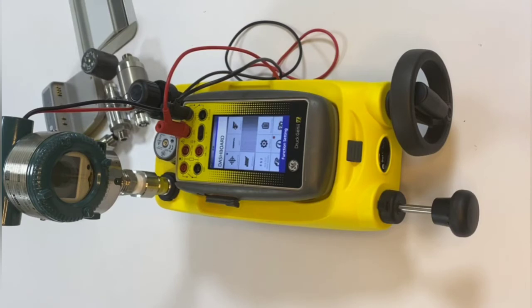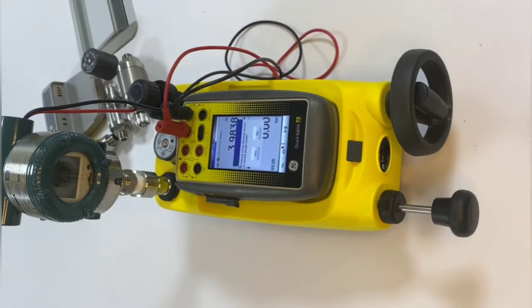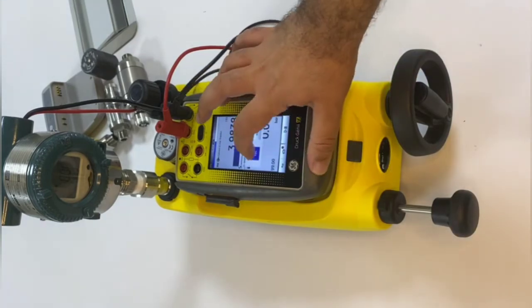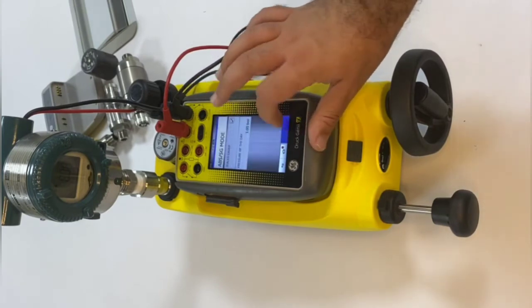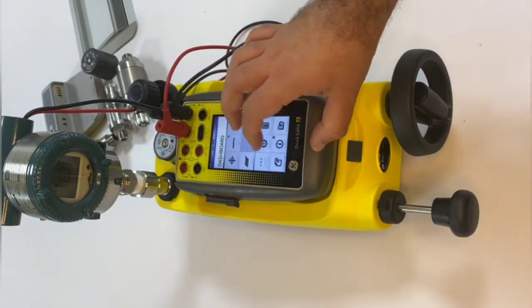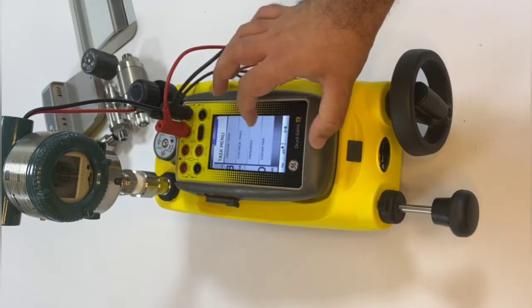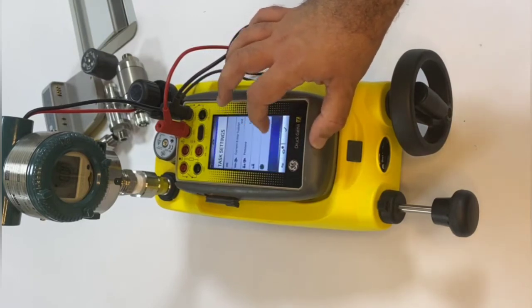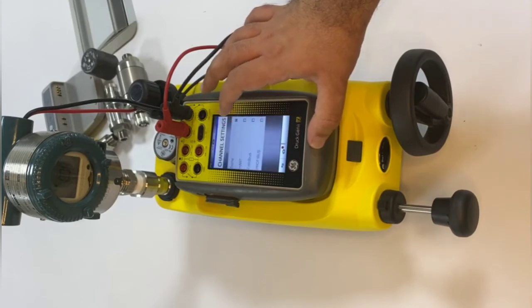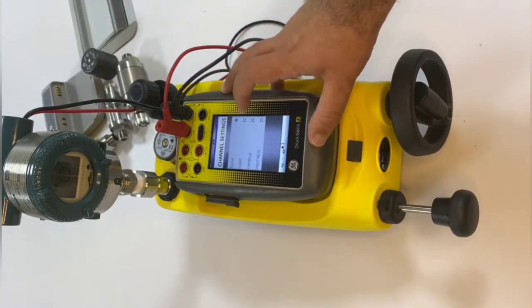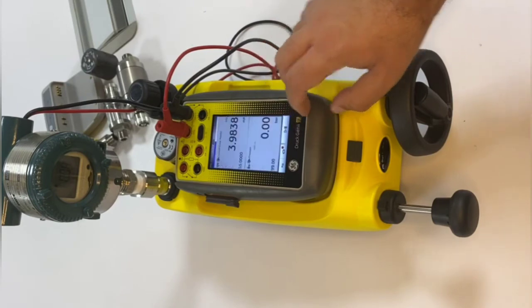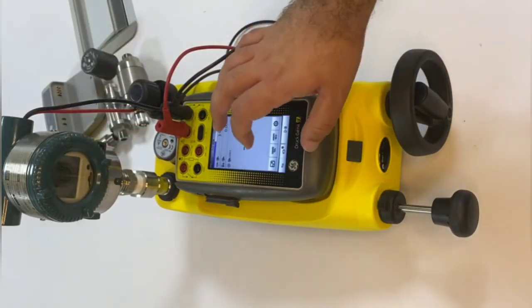So in HART devices, you either have potentiometer here to perform zero adjustment or full scale adjustment. You can make a zero trim, pressure trim, or you can change other functions. So we will come to see that together now. So here is our HART menu. We will select here HART. As you can see in the device, there is HART, Fieldbus and Profibus. In my case, I'll use the HART because my transmitter is HART transmitter.